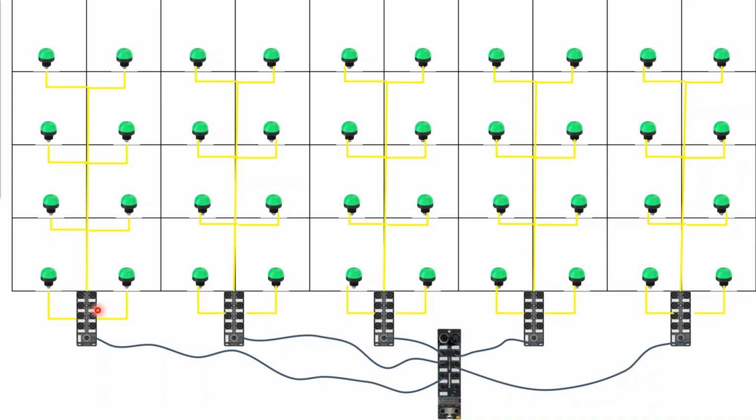So using my 16-port discrete IO hub, I'm able to take a cable from this block here on the right side of the board that's got 8 IO-Link master channels. I can take a cable up to 20 meters to this hub, and this is just discrete IO wiring. So I was able to do this entire thing without landing a single wire, taking advantage of what the IO-Link has to offer, and only using one IP address.